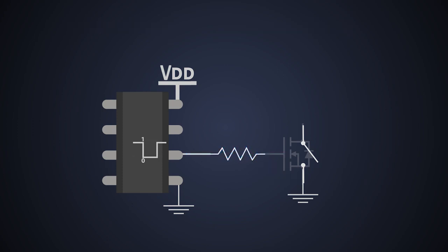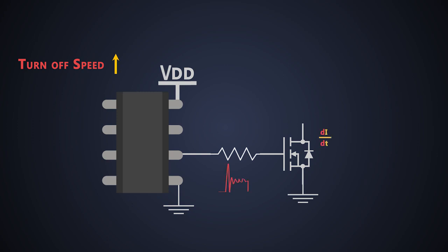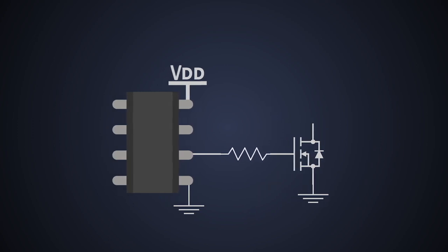While faster switching can potentially lower the switching losses, when we increase the turn-off speed, ringing in the waveform occurs due to the higher turn-off di/dt and dv/dt of the MOSFET. This is something to consider in selecting the proper voltage rating and EMI containment of the power device. We'll focus on the techniques which increase the turn-off speed of the N-channel MOSFET when it is used as a low side switch.